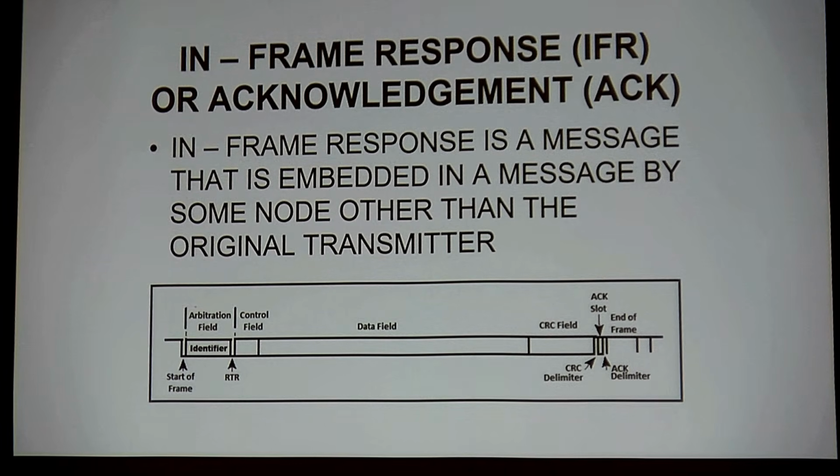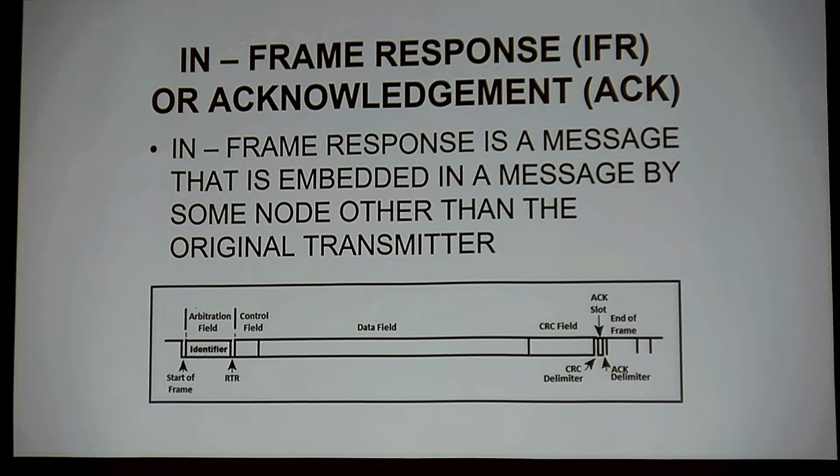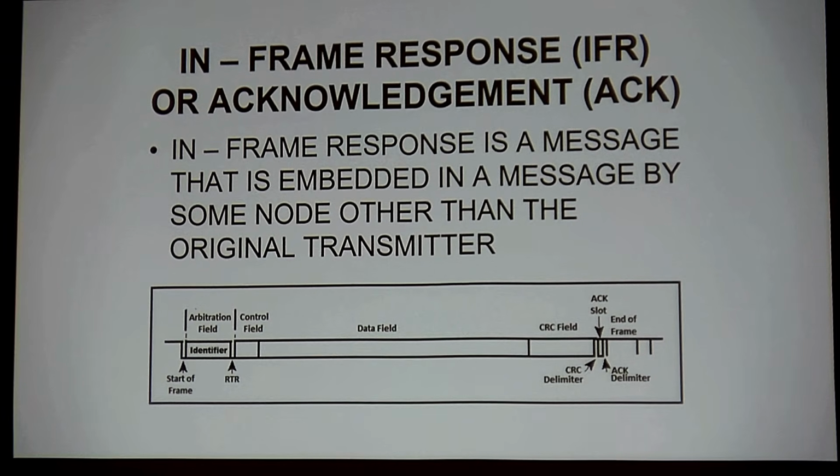And the next piece is an acknowledgement. This is referred to as an in-frame response or an acknowledgement. So in CAN, they want somebody to be able to say that they heard the message. I got 40 modules out there. In real cars, we might not have 40, but we're going to use that as an expression. Might have 3. It really doesn't matter. I need somebody out there to acknowledge they got the message. Now, there's no way that they had any time to evaluate the message to know if this message is good or bad.